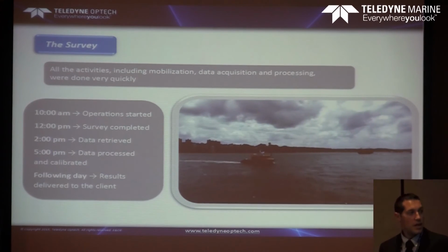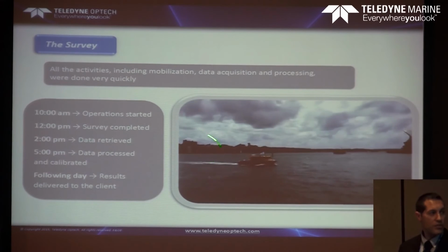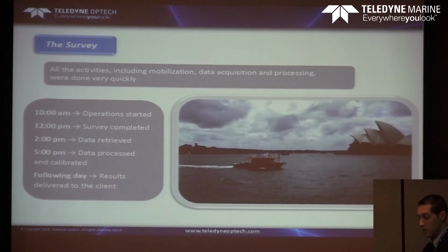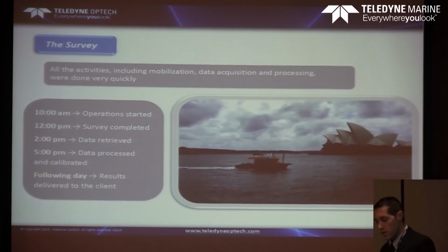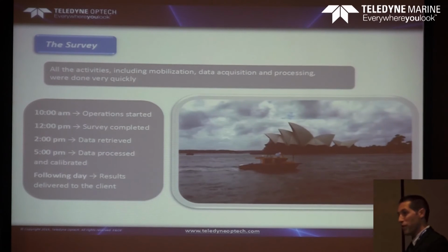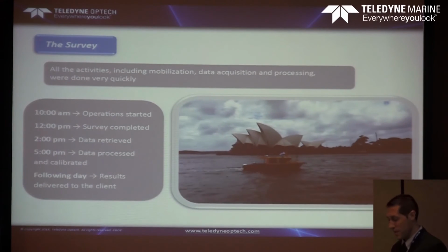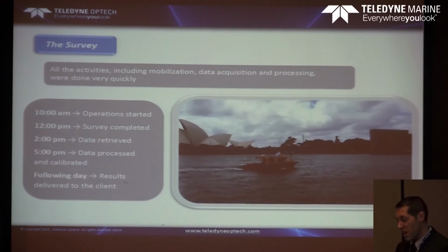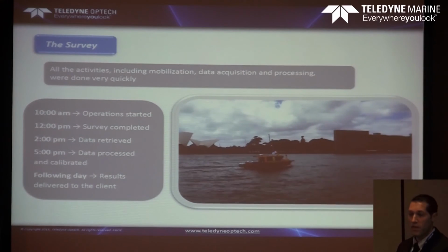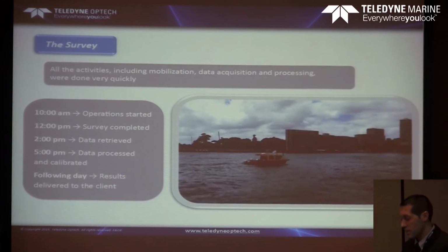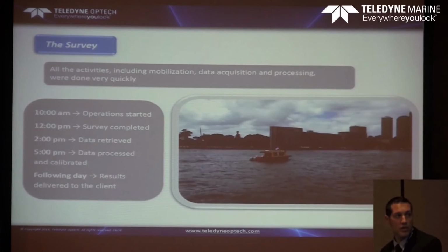Then, after 2 hours, we retrieved the data set from the hard disk of the computer inside. It's a lot of data, of course. 2 hours of survey from both bathymetry and laser scanner is a lot of data that you collect. You do the processing. It took 3 hours, and at 5 o'clock everything was already calibrated. We actually delivered the data set the day after to the Port Authority.